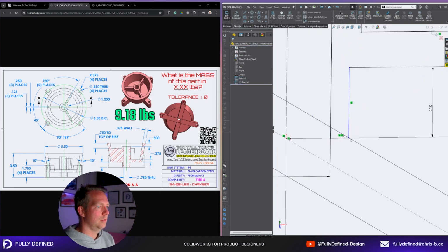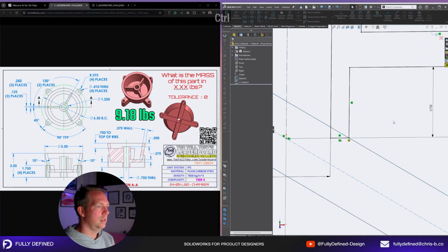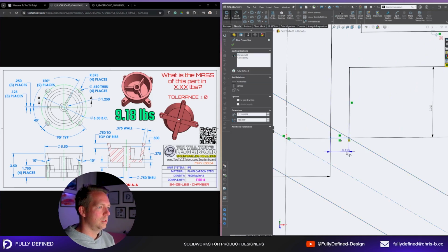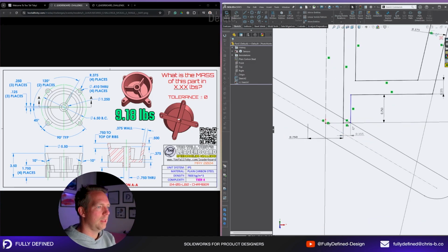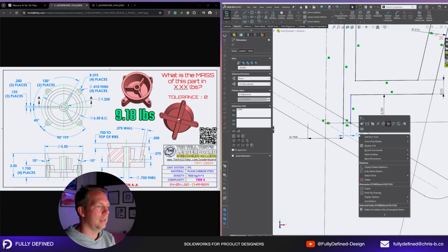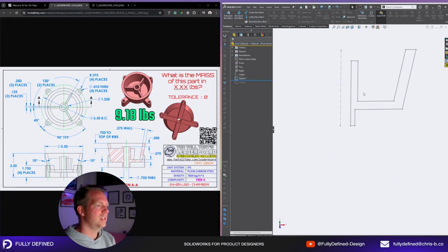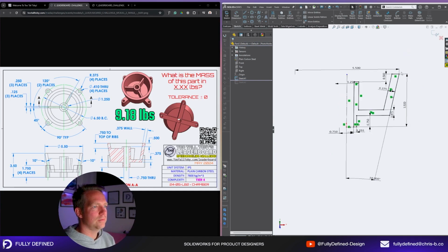So now we can go back to this first sketch, and can I drop it below? Yep, drop it below. Drop it on that point so it's piercing, and then I've got the dimension. 0.155. Oof, that's what it is. Get rid of that. Make it driven. I'll use that later. But let's finish this sketch first. So that sketch is fully defined.